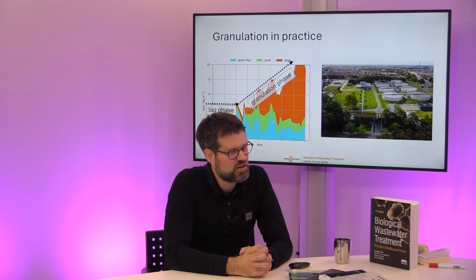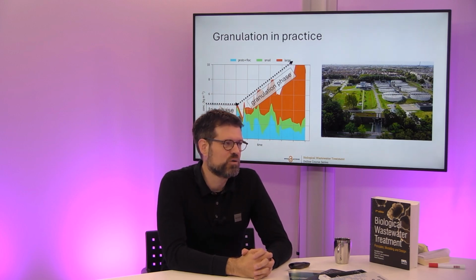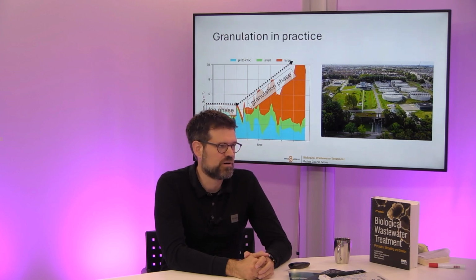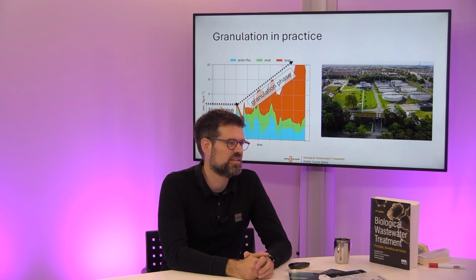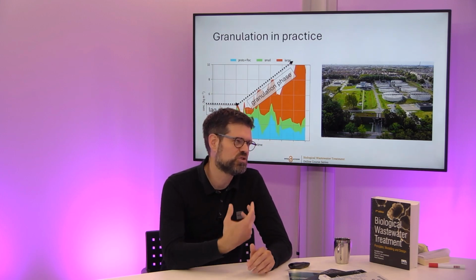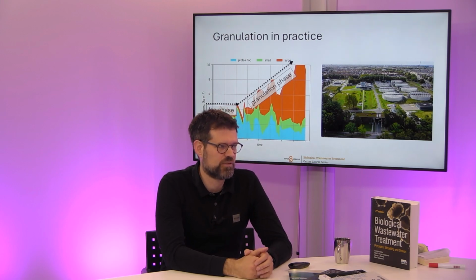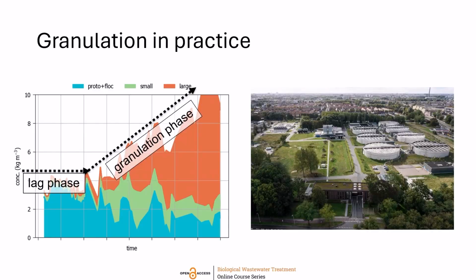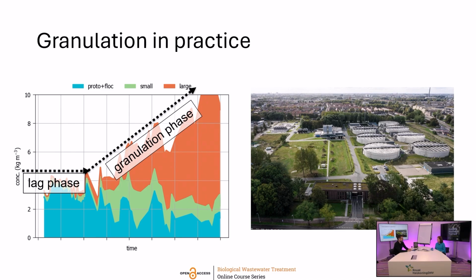A few years ago, we had a lot of questions about how the granulation works, and I'm showing a photograph here of one of our bigger plants in the Netherlands, the wastewater treatment plant of Utrecht. We did multiple startups of Nereda reactors where we seeded with flocs and then tried to grow granules in it, and we always got a similar behavior. And we had a lot of questions about that.